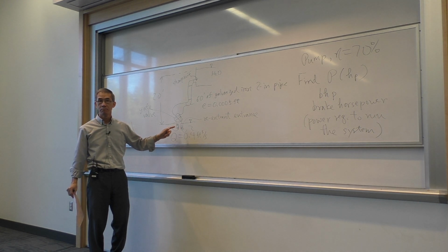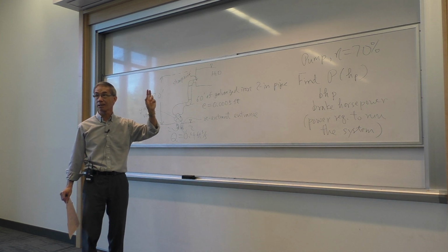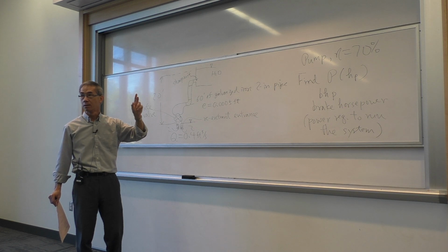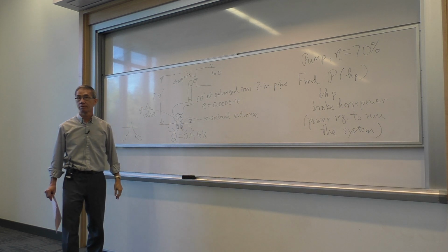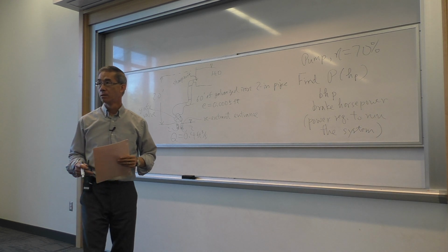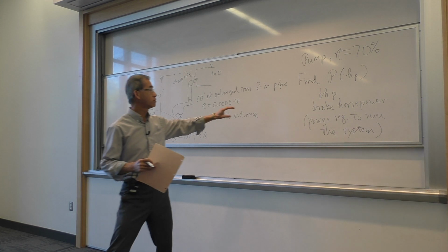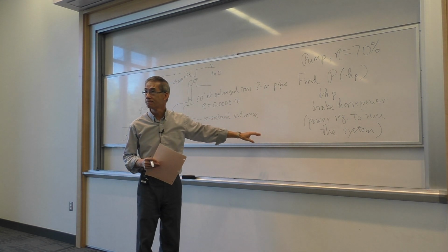That's pressure loss. So for an aircraft engine, where every ounce of weight is accounted for, not even pounds, you want to minimize those losses. Yes? So how will we know when to account for minor losses? You always have to, for any realistic flow system. How to account for it is what I will show you next. Right?